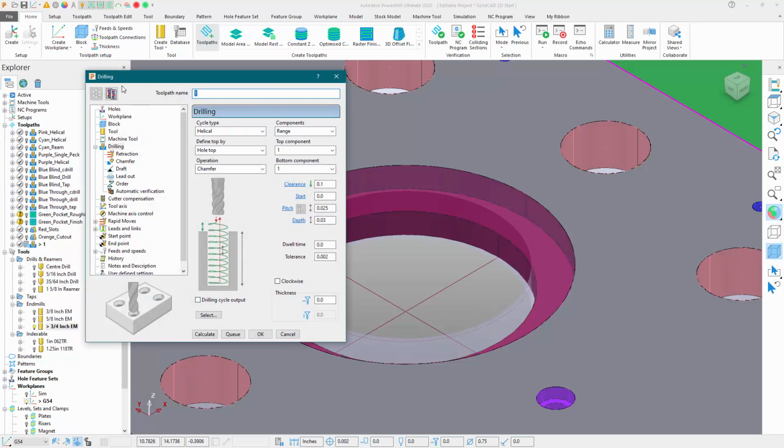I'm going to call this one Ring Center. Now I'll only concentrate on the second component, which would be this interior. I want to focus on the top of the hole, and I want to cut to the hole depth. The pitch, make it rather large, 1/4 inch. I'm not going to leave any thickness since this face really doesn't mean anything. I'm going to cut it right to 0.